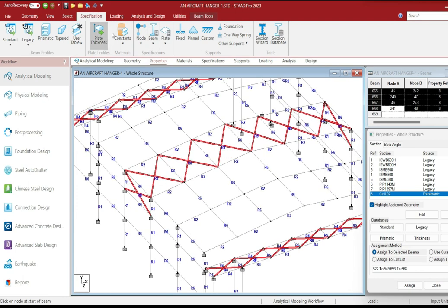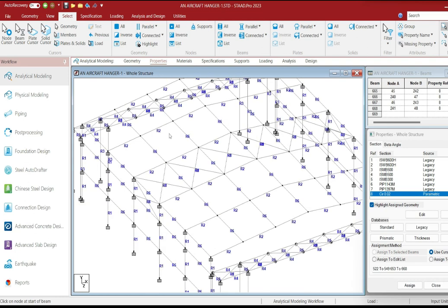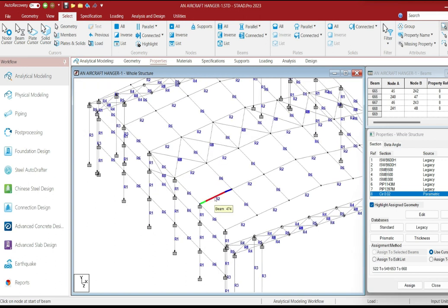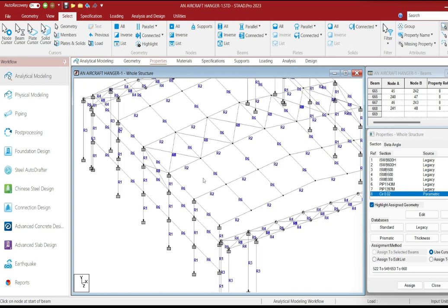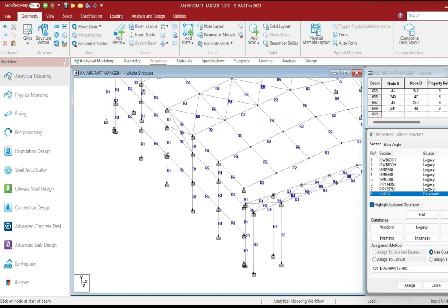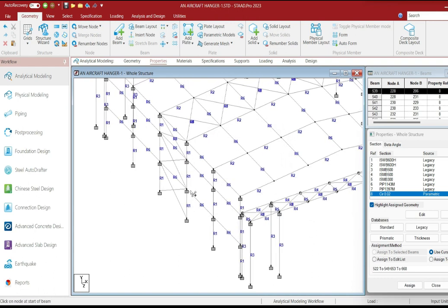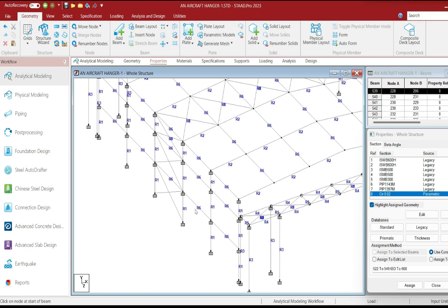Now below the crane bracket level, we should have pipe section or tube section as a bracing member, because the crane creates vibratory longitudinal forces. So it is recommended that we should not provide rod bracing below that. Pipe bracing or tube bracing is more suitable to take this kind of vibratory load. So obviously, for this model, we will take them as tension member only, not as a truss. So their stiffness will obviously be much higher than the rod bracing.